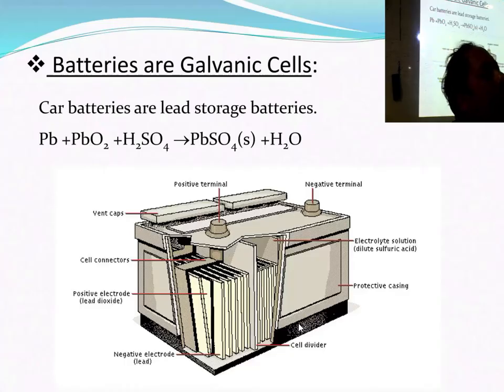Very high melting is actually disadvantageous, because whenever it is high melting, you have to use a lot of fuel to raise the temperature. That is not economical, number one. And if you go to a higher temperature, there will be more and more corrosion and damage. The whole system damages faster. So that's why you always have to look for a material that is durable, convenient, and allows low temperature casting. That is the material science. That is the reason we are choosing lead.